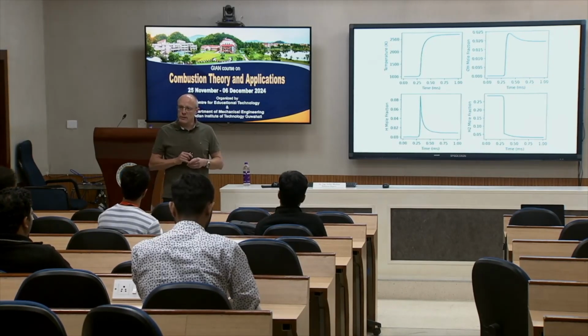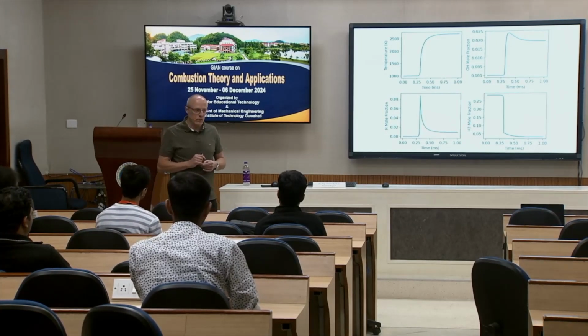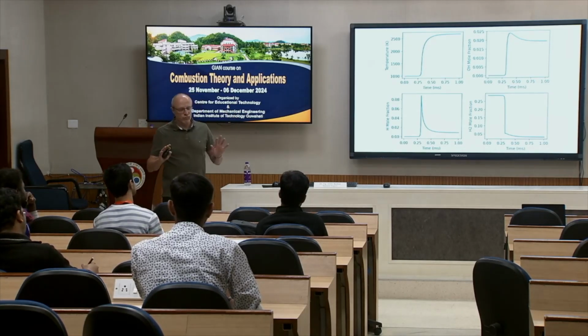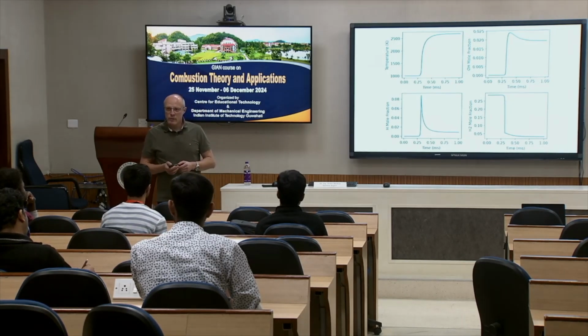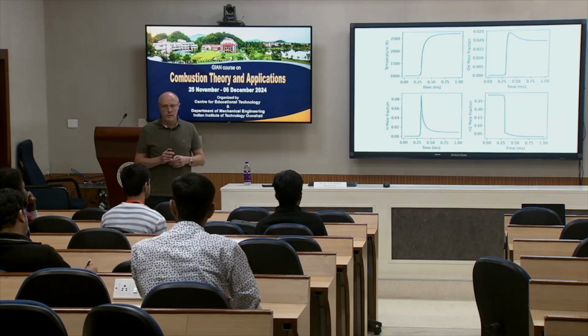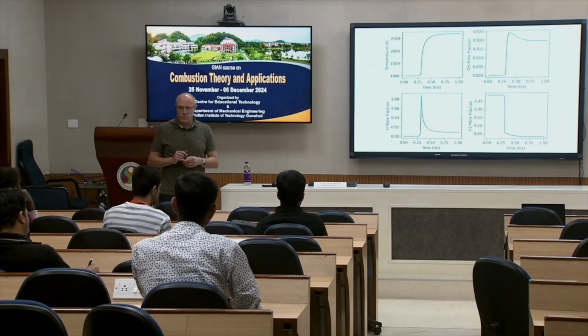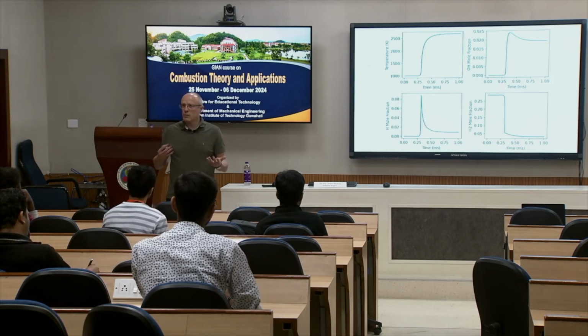We can use specific laser diagnostics, so-called laser-induced fluorescence, and OH is very easy here. For H we have to use specific, very complex configurations. 2-photon laser-induced fluorescence, so it's much more complex. That's the reason why we use OH, because it's so easy.